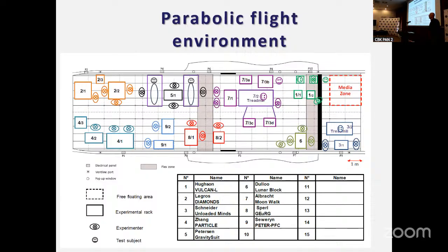How did you contain an experiment like yours? You know, the RCE is small, but the issue here, I forgot to mention on the slide: the mass of the RCE is just 2 kilograms, but the full mass of our experiment rack is 150. So we are using 140 kilograms just for the mechanical device, mainly to reset the regolith, to reset the relative density, etc., to repeat the experiment in repeatable conditions.